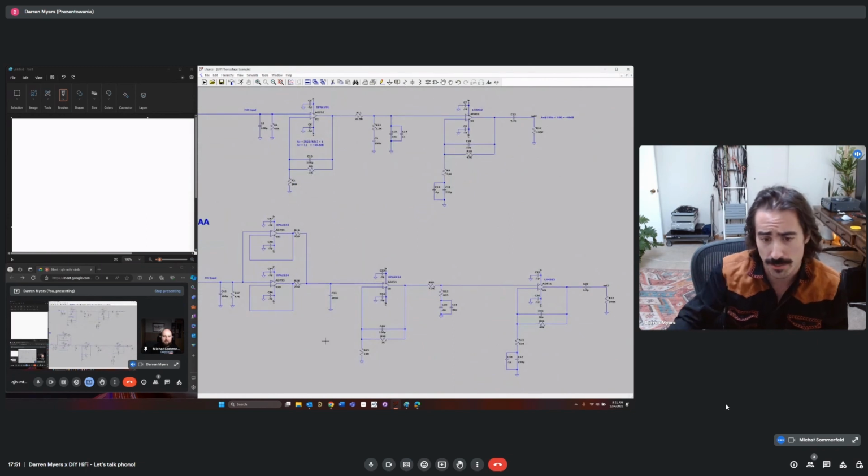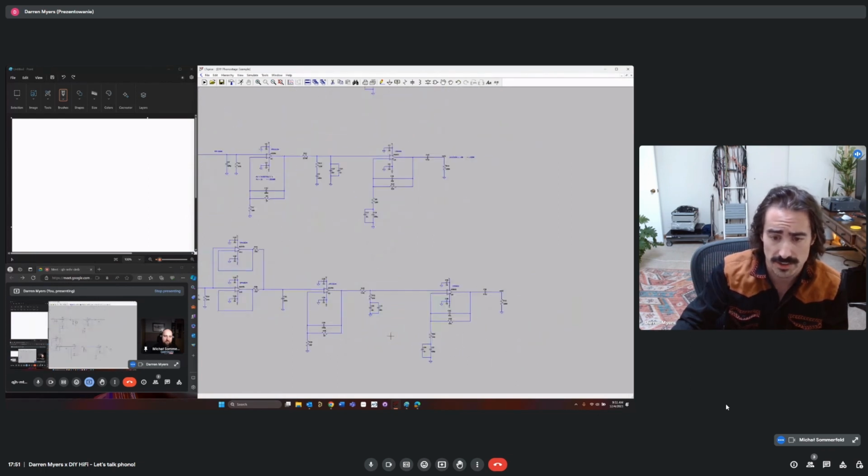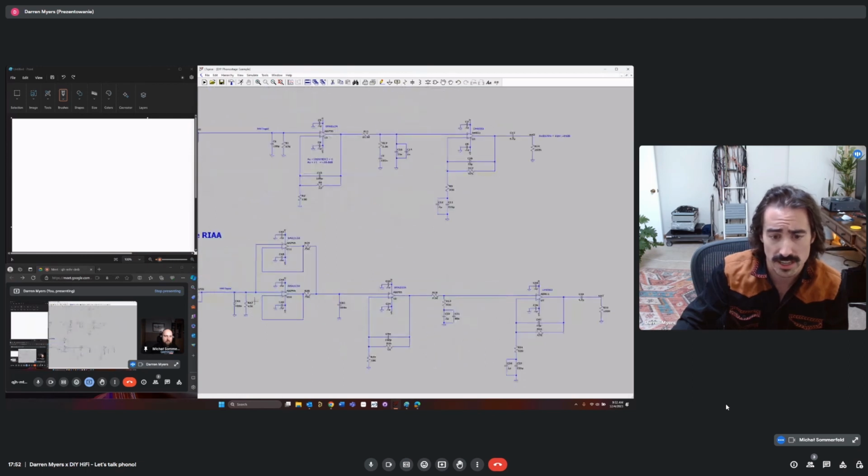That's a good compromise to be able to drive this impedance, keeping it low and dealing with that noise. Just remember that your buffer also does need to be relatively low noise. You don't want to use something that's like 20 nanovolts here. You want to keep it low. But if you use the 2134 and parallel it, that now cuts it down 3 dB.